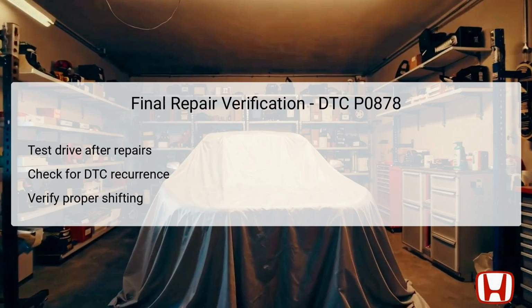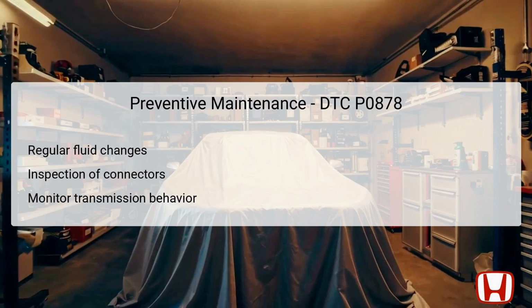Additionally, verifying the proper function of all transmission components reassures the technician that customers will not encounter further issues stemming from the original fault. Preventive maintenance plays a crucial role in avoiding issues like DTC P0878 in the future. Key aspects include conducting regular transmission fluid changes, which help maintain optimal hydraulic functionality. Ensuring that all connectors associated with the transmission fluid pressure switch are free of corrosion or damage plays a significant role in ensuring reliable performance.